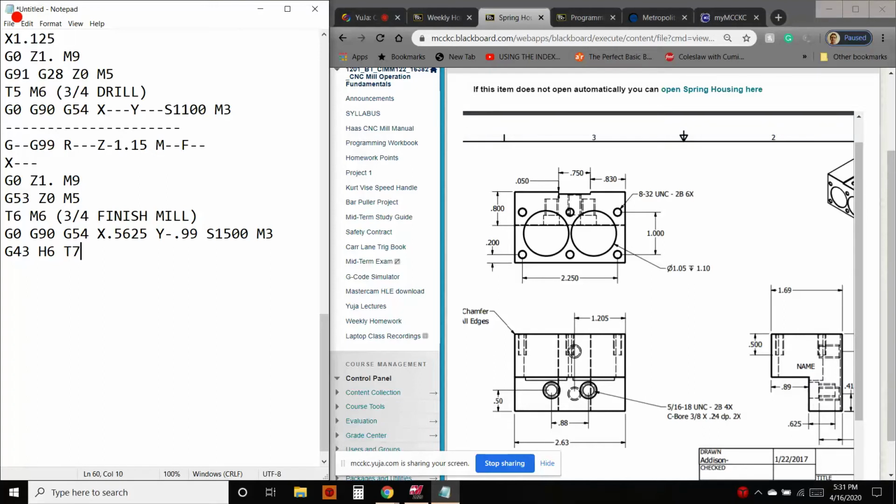T7. And we're going to use cutter compensation so that when we do pull out our chamfer mill, we can use the exact same program. Remember how we were doing that with the cam arms, that we'd run around it with the hog mill, the finish mill, and the chamfer mill, all with the same tool path. And simply by changing the D values, you can run the same tool path, save a ton of time, and everything looks perfect because it's the exact same tool path.